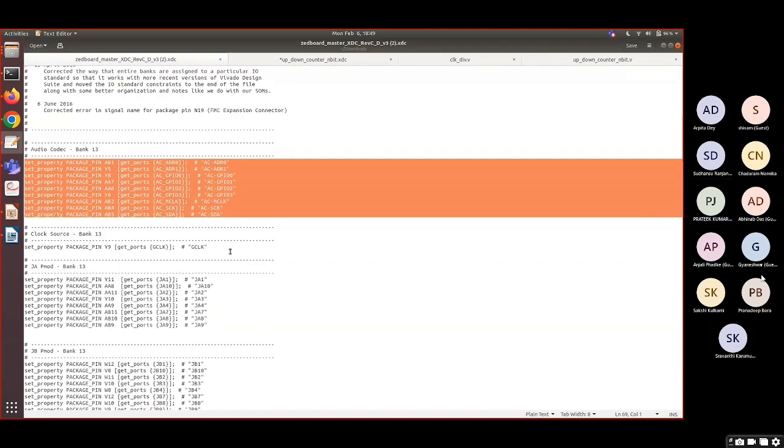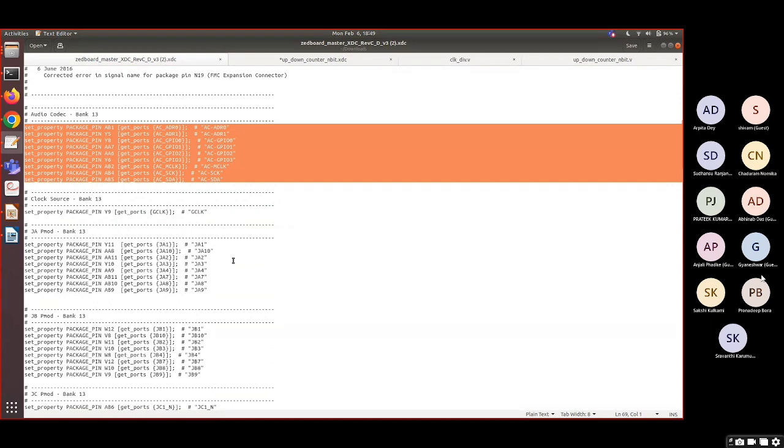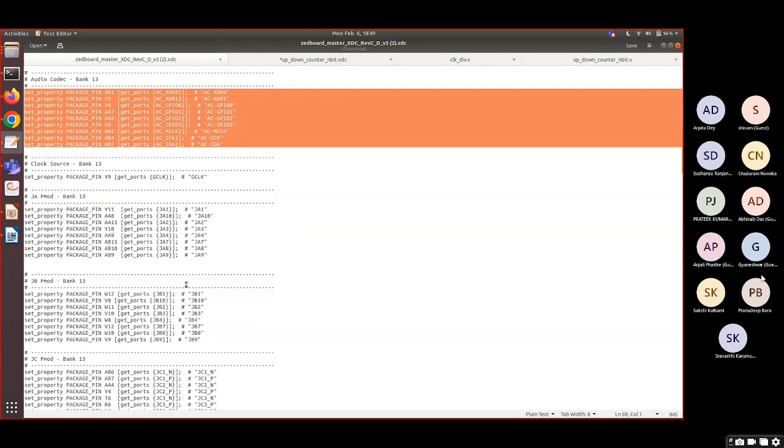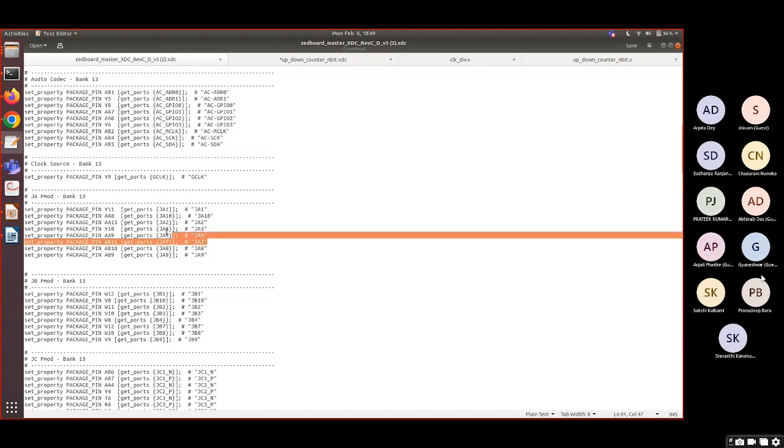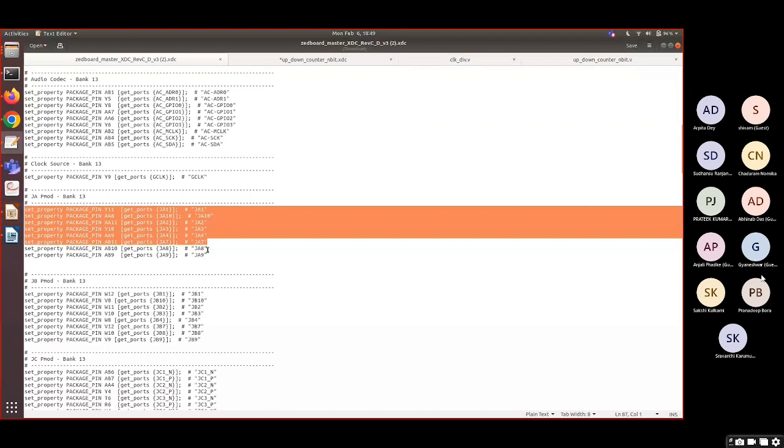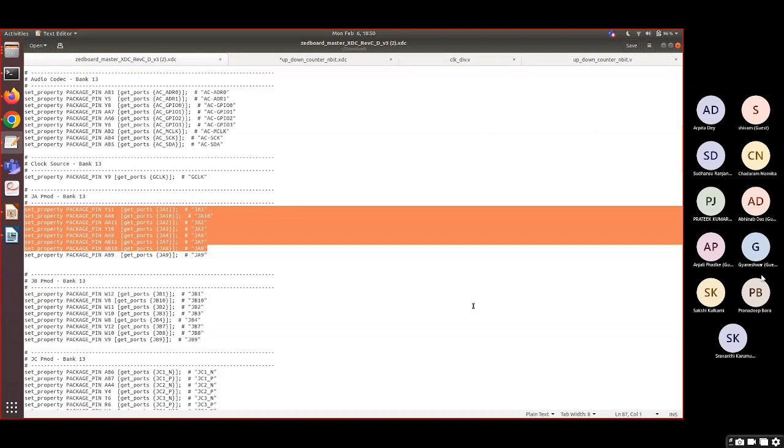Let's say I'm giving a simple example. I want to connect a 7 segment display. For that I need 7 inputs, right? Out of these generic peripheral inputs, I'll be using 7 inputs. Depending upon the requirement, on a case to case basis, we need to connect peripherals, but those peripheral pin configurations should be the same.